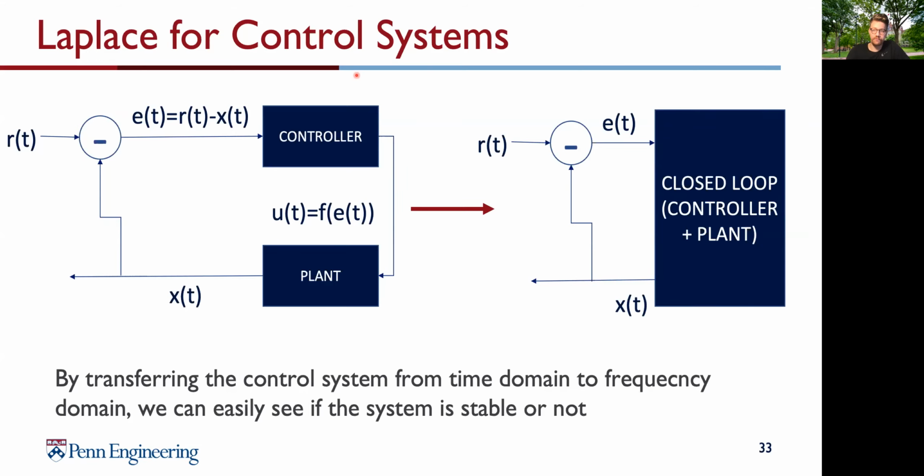And what we do now is create a transfer function. The key advantage of the transfer function is, again, its compactness, which makes it suitable for frequency domain analysis and stability studies afterwards. The transfer function itself suffers from neglecting initial conditions. Not only does the state-based representation serve as an alternative to these transfer functions, but it is also not limited to linear and time invariant systems, and it has the following advantages.